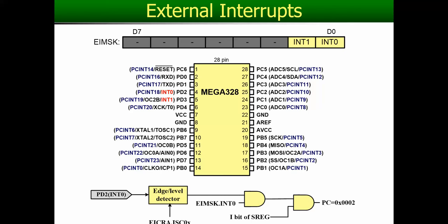It wants you to go to that main office, to the keyboard, and pick up the key. So whatever turn was next, you're not going to the next instruction. Rather, you're going to the fixed location 0002, in this case, in the INT0 case. Now the question comes: let's say we took the key, we went to the room, we did that task, we brought the key, we put it back on the keyboard, but how would I know where I was interrupted so that I can resume the previous work?